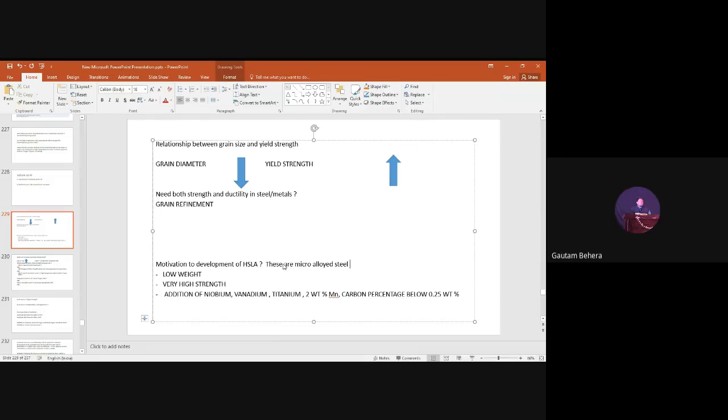What is the slip plane and slip direction in FCC? Because a slip system is a combination of slip planes and slip directions, right? How many of you remember? The 111 plane in the 110 direction. Very good. If you have a cube, can you tell me the plane, from where to where it is? I'll give you a cube and ask you to draw a 111 plane.